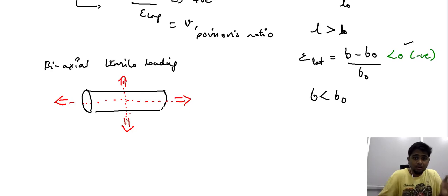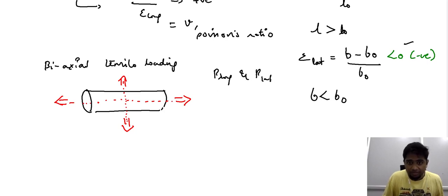So we have now a longitudinal load, and in addition to that we have a lateral load. So we are moving away from the straightforward consideration of just the uni-axial tensile loading to biaxial tensile loading. Biaxial tensile loading essentially means that we are imposing load along the longitudinal direction and also along the lateral direction. So once we are able to quantify this load, by considering the corresponding dimension, we will be able to quantify the longitudinal stress and also the lateral stress.